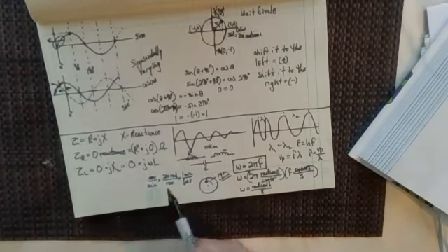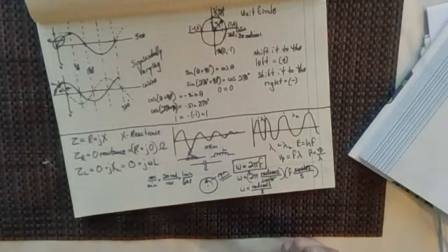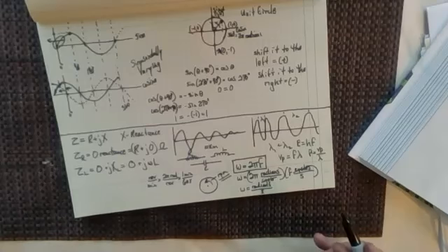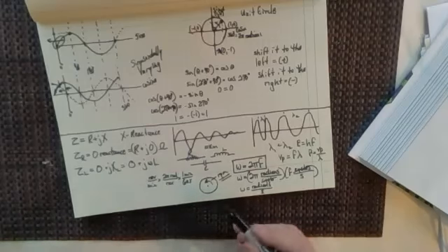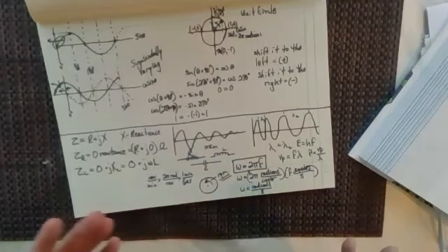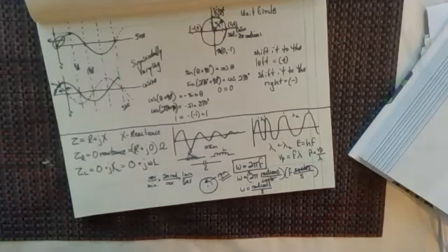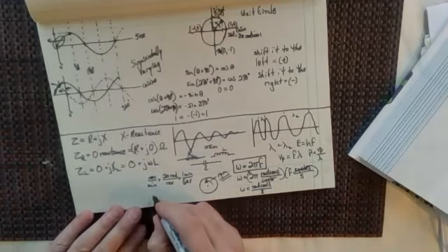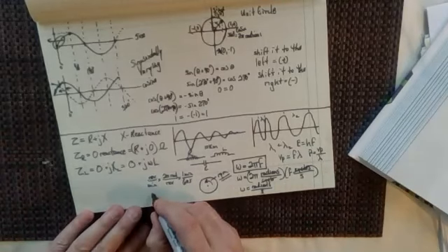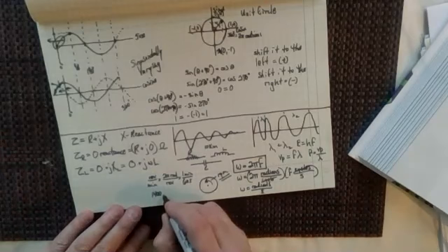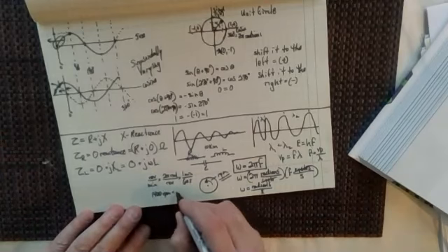You can almost see the 2 pi radians is 6.28, isn't it? And 60 is about 10 times that. So really, we're going to be dividing this by 10. That's a good rule of thumb. If you ever have revolutions per minute and you want to convert them into radians per second, you're going to end up dividing by 10 approximately.